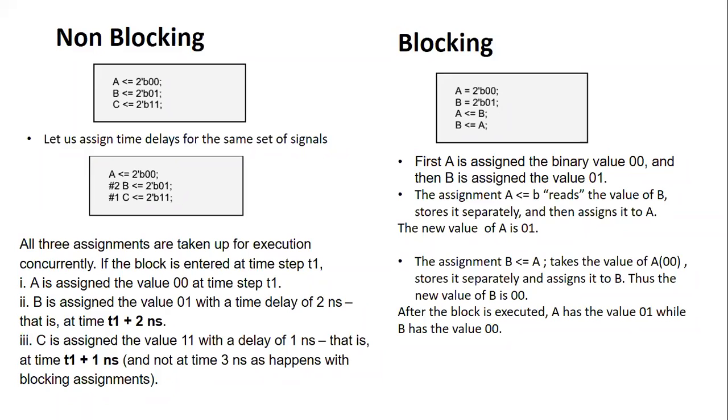at the particular time. Now if I put a delay, so I put a delay over here. What is the delay I've used? 2 and 1. So what happens? Again, if you can see, they're all non-blocking assignments. Less than or equal to represents non-blocking. So what will happen? All the statements will be executed at the same time. A will be equal to 00.